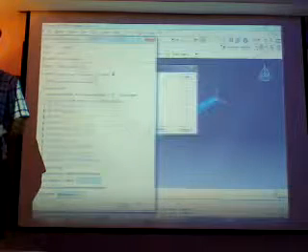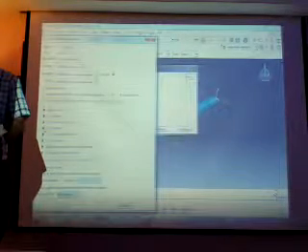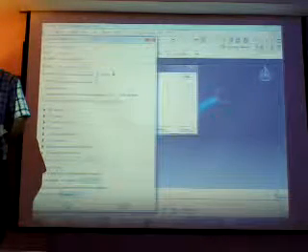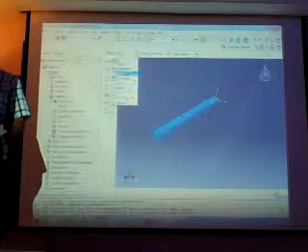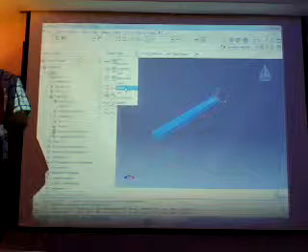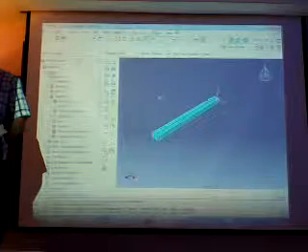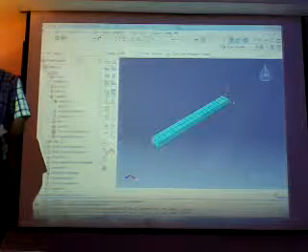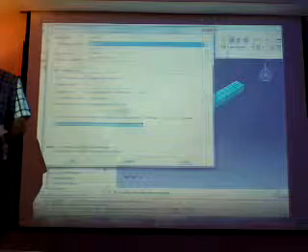And here is your output. If you need any specific output, for example, if your simulation has a thermal change, you can here take a thermal. Okay. All the things are the same, just here we need to change our mesh type. As I told you, the part here, you can see the element library is standard. Now it's necessary to change it to explicit. Now this is explicit. And you can see here again the name of the mesh.